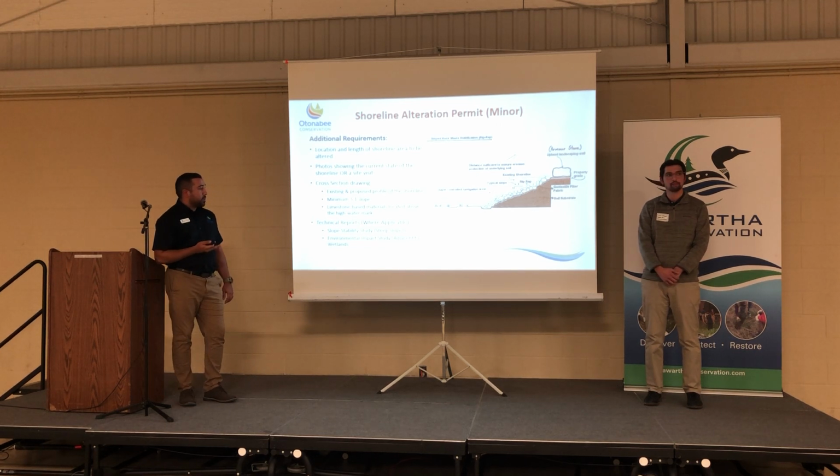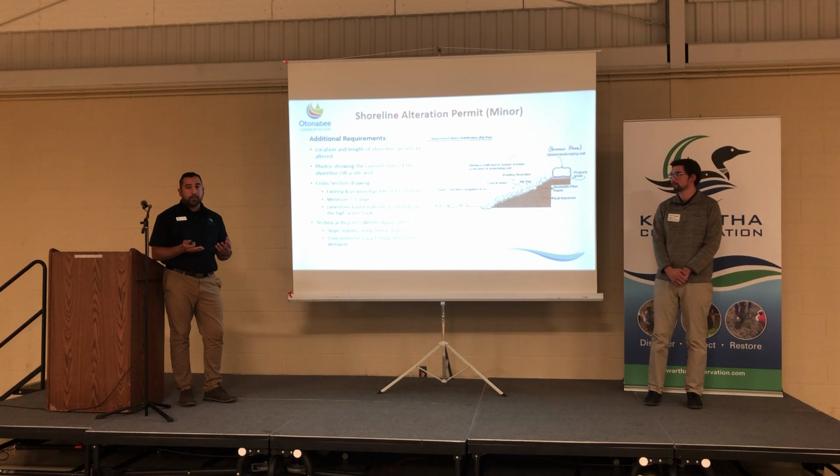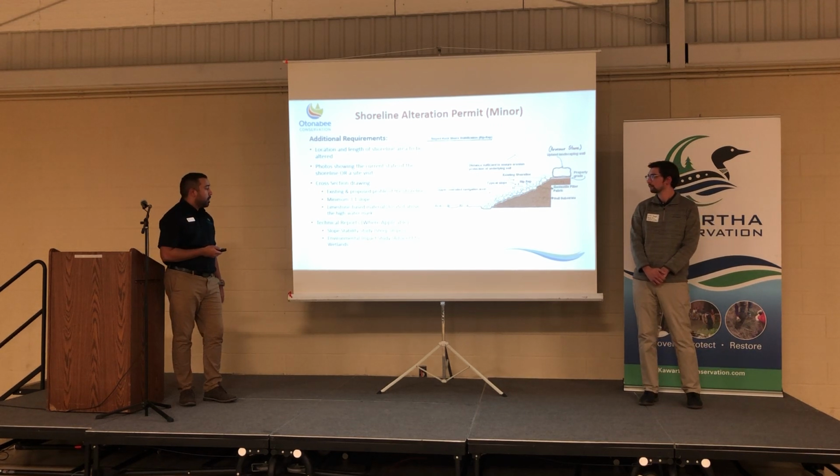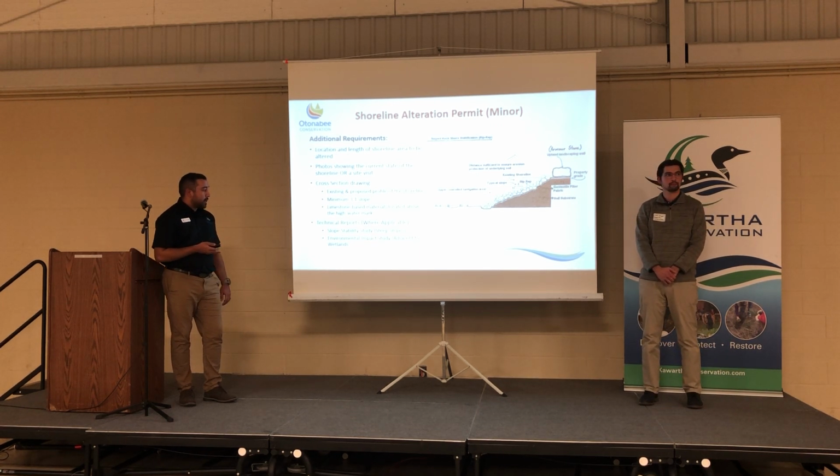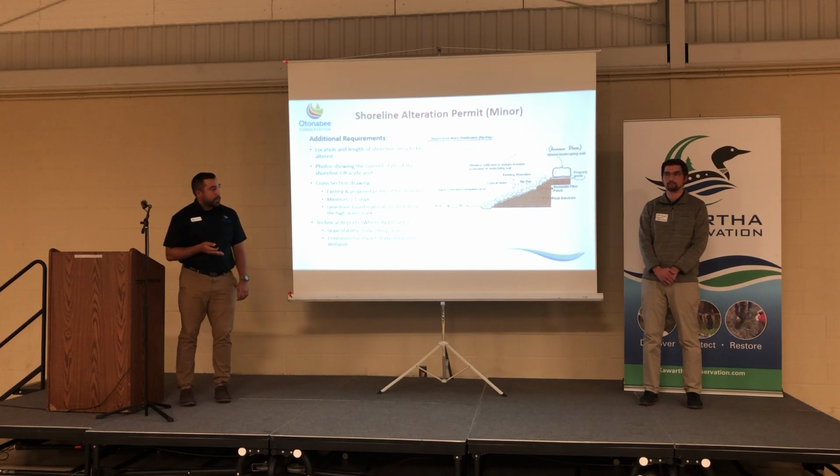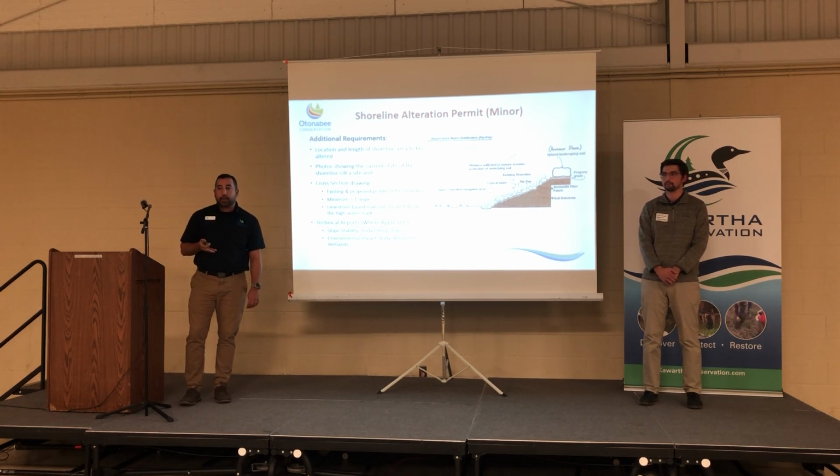Environmental impact studies could come into play if you have wetlands either on the property or adjacent. This actually does happen quite often for shoreline properties where you have marsh areas within the water body itself. So with the environmental impact study, we're mostly looking to make sure that the work is not going to impact the wetland in any way, specifically with the hydrologic function of the wetland.